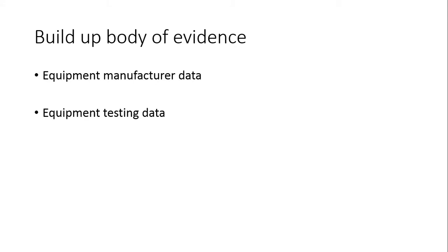In some cases, if you're bringing in a new piece of equipment, especially relative to thermal processing, but in other cases, a novel pasteurization methodology, the equipment manufacturer, because they want to be able to sell this, may have already built up a research database showing that running the equipment under certain conditions is going to provide pasteurization or death of various organisms under certain run conditions. And equally too, when you're commissioning new equipment, you may be wanting to collect testing data off of the newly processed product coming off of it to ensure that there's not any contamination.